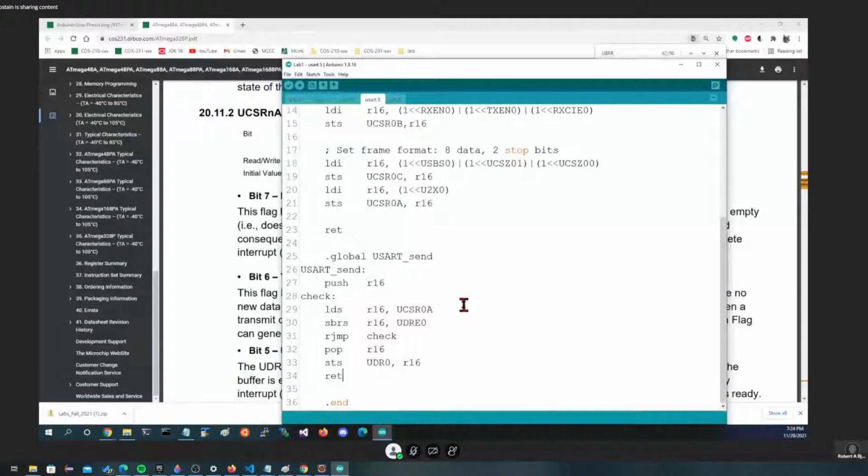I'm guessing it's for modularity and reusability of the code and to clean up our code. It's just making helper functions. Right. This turns out to be a utility function, but it's so related to the USART, we might as well stick it in with the other USART code. However, the receive interrupt, although it's USART related, is not universal. It's specific to a program. And so for that program, it makes sense for it to be in the program with that code. And so that's why we don't see the USART receive code here. We only see the send code.